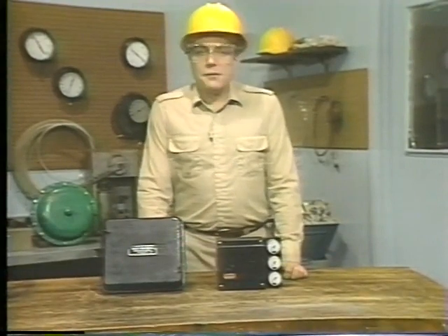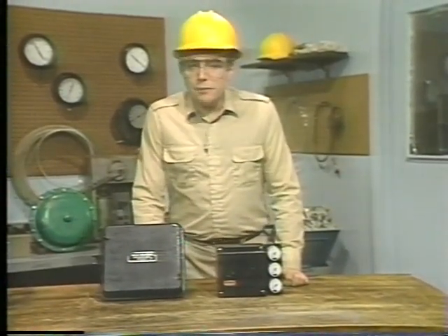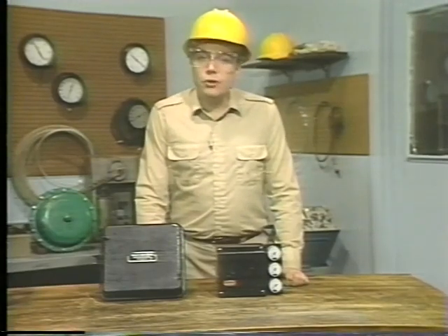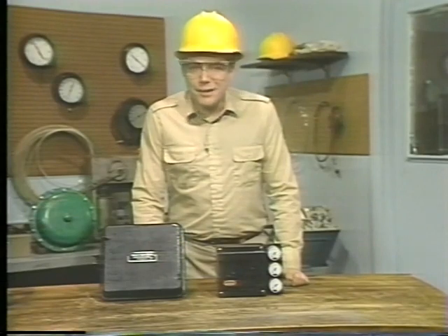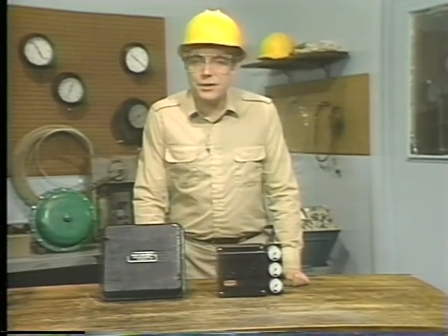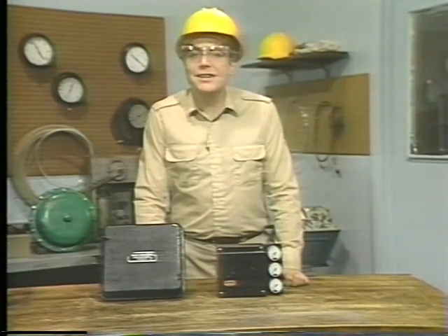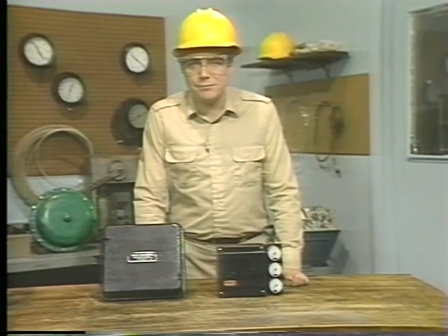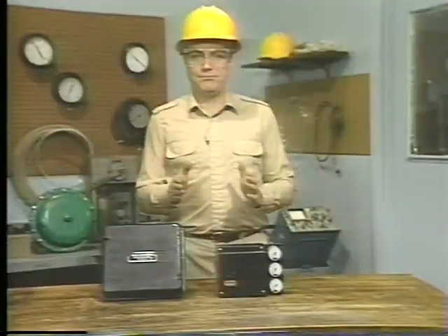You may remember that the function of a pneumatic positioner is to respond to a signal from a controller by regulating airflow to move an actuator to a specific position. If the actuator does not move the amount specified by the signal from the controller, the positioner will compensate by allowing more air to flow to the actuator until it does move to the proper position. Then the positioner will shut off the airflow to stop the actuator and hold it in place.